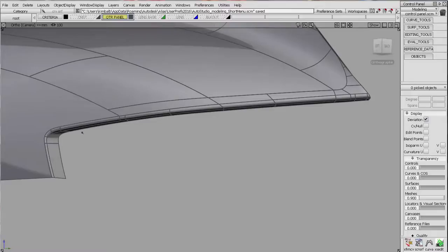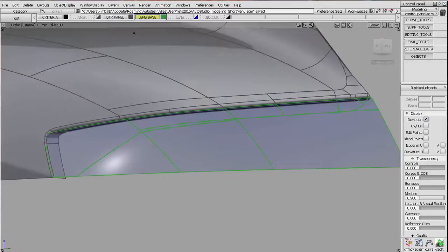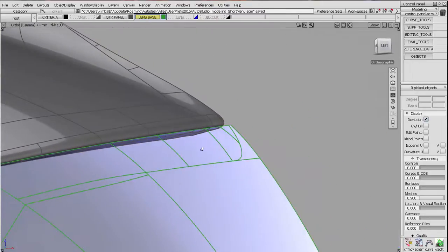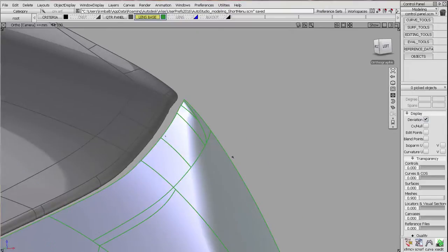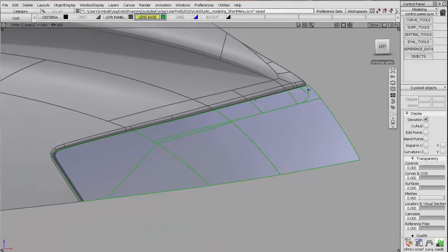Let's move on from the quarter panel to building the edge of the lens for the rear tail lamp. That starts with this base surface, which is up here at the same height. So this surface and this surface were the same. Now we've just trimmed this off, right? And we need to come back in here, and based on some criteria, we need to underflush this lens, and we need to create the blackout.